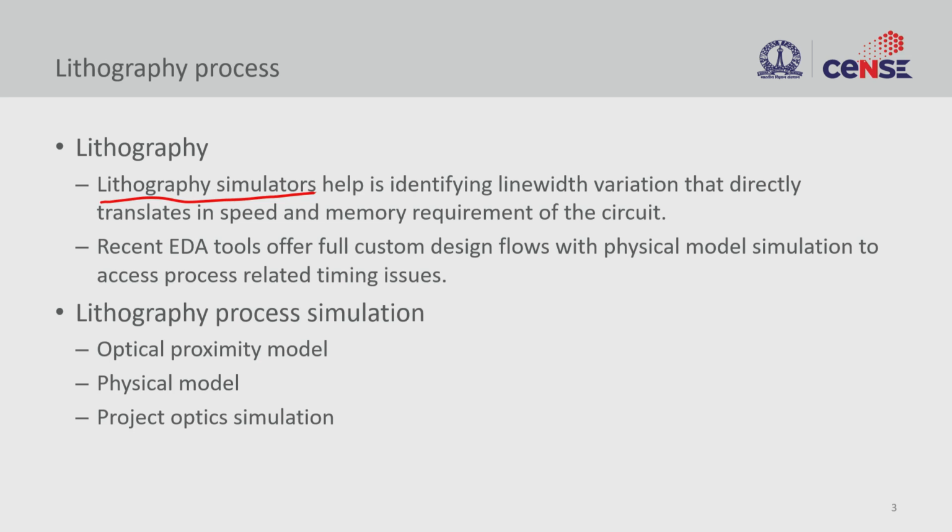And then when you run these simulators on your design, if you make a certain design, we will run it through the simulator and see what my image on the photoresist will be. It might be something like this. We want to understand the effect of the edges, the effect of the corners, and then use this to understand the parametric related problems.